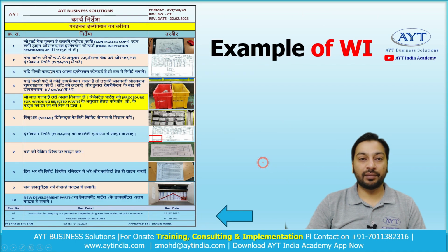Now we will talk about level 3. In level 3 we see a work instruction. The complete method of final inspection is described here. What should I do if I have to do the final inspection? First of all, check the control copy of the part you are checking. Take the stamped drawing and the final inspection standard from your file. Check the dimensions of 5 parts according to the standard and fill in the final inspection report.